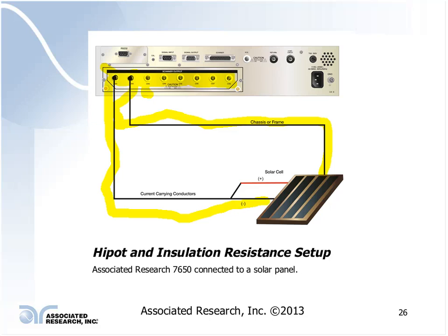Then, in an automated fashion, I can internally in the unit on the second step have it automatically flow into a second test where high voltage is applied here and the return point is applied here, thus effectively doing both polarities in a single shot.